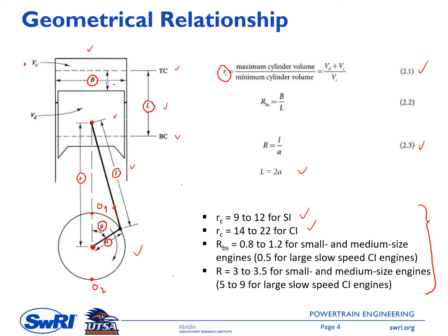For the heavy duty compression ignition engine, we have compression ratio close to 19 to 1. And I believe last year we did a short research looking at the compression ratio of 22 to 1. But for this high compression ratio, we need a different material for the cylinder head because of the increase in peak cylinder pressure.